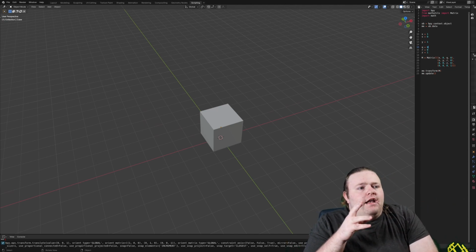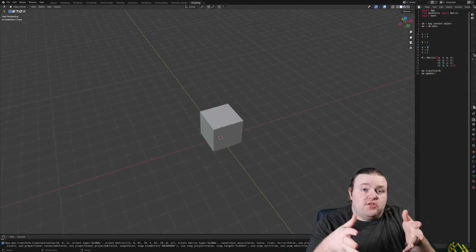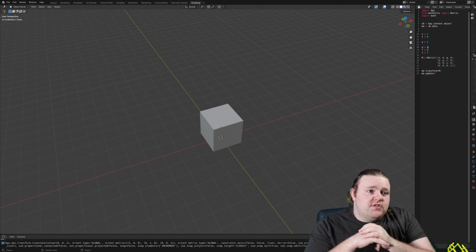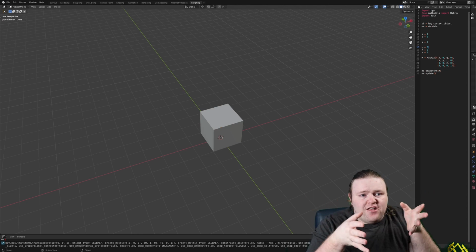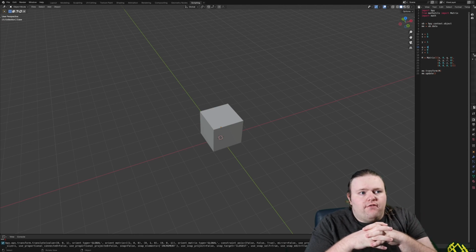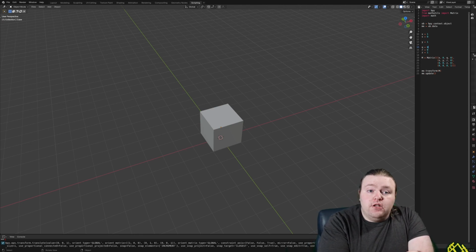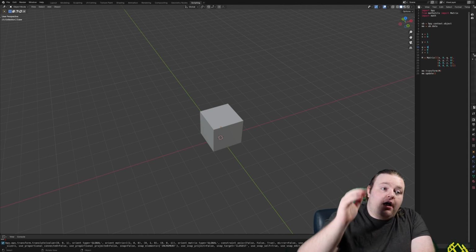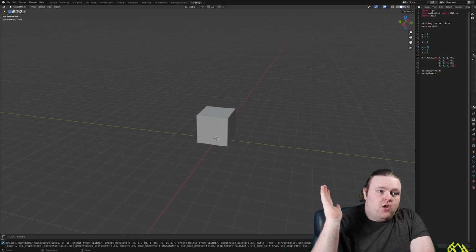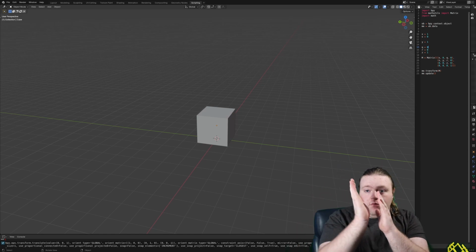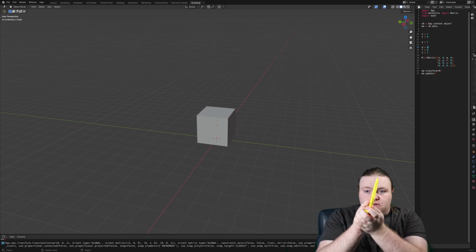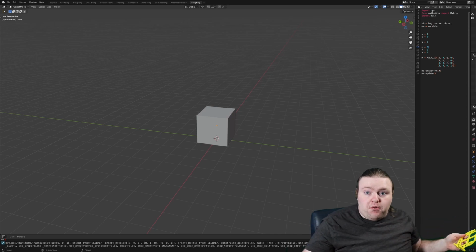So that is the first problem: we can correct skew in the XY plane, and in fact, it's the easiest plane to correct skew in. So it is tangible, it's easy, or easy enough. But there are two other planes that have other implications on the quality of prints. As the print head is moving up in the Z direction, and we have skew in relation to Z, then we're necessarily shifting layers, right? We're leaning the part. The part should be straight up and down, but it's doing this as it goes up. And that is also a problem.